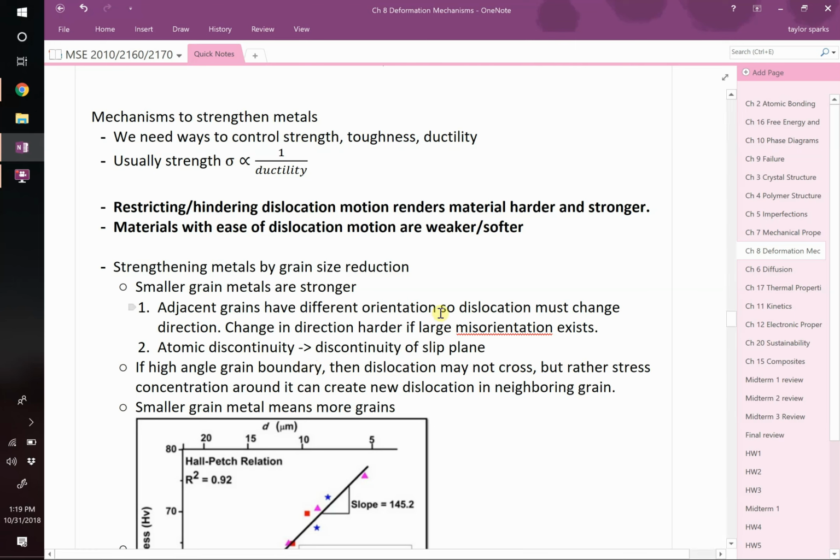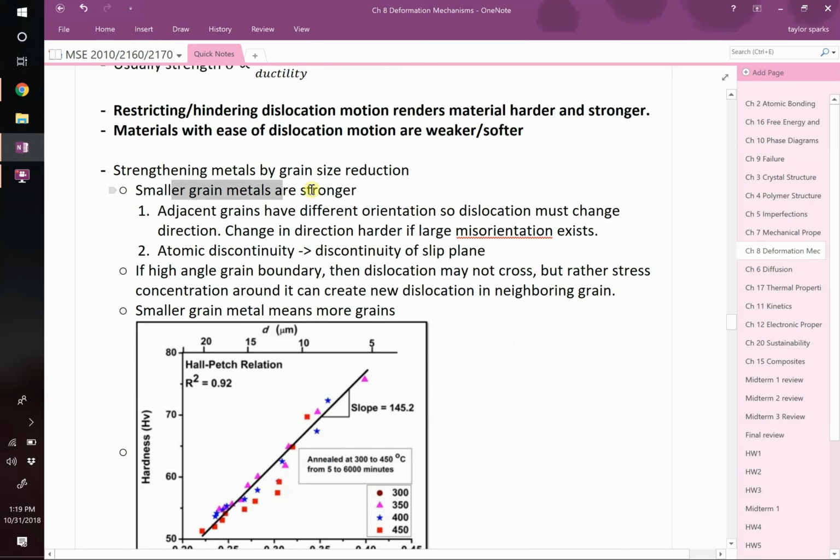Okay? So one way that we can control that relationship is with the grain size, right? Grain size. So smaller grains are actually stronger. That might seem a little bit counterintuitive, but smaller grains are stronger. And the reason why is because within a single grain, as atoms start to slide past each other, in a smaller grain, they're going to hit a grain boundary sooner. If they hit a grain boundary sooner, the odds of the two crystals next to each other being perfectly lined up, that slip can just keep on going because it's a nice perfect lineup, that's pretty low. It's probably going to be rotated off a little bit, so that slip's going to reach the grain boundary and have to change direction, or it might get pinned, or it might get dissolved, right? It might fix itself and heal itself and the dislocation goes away.